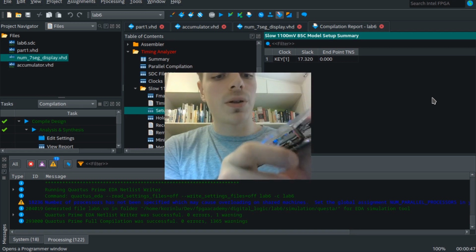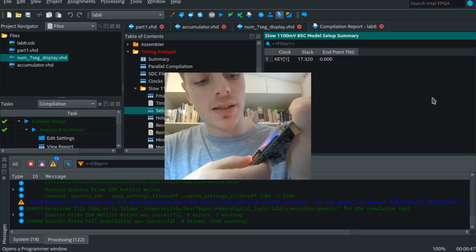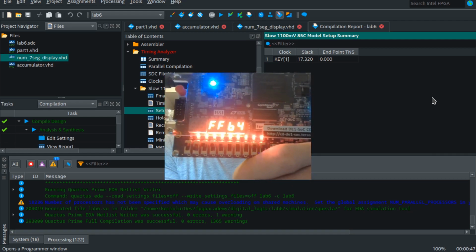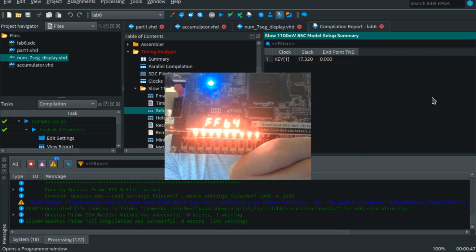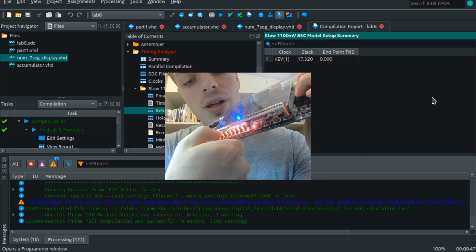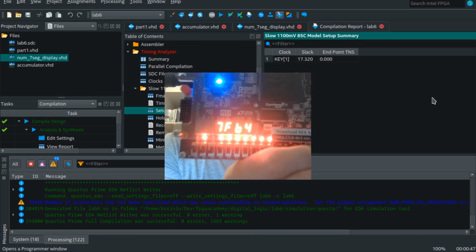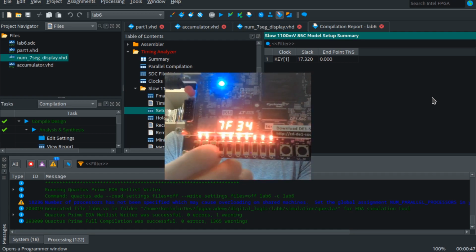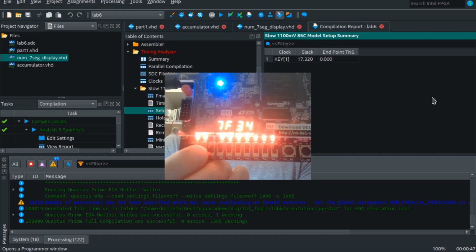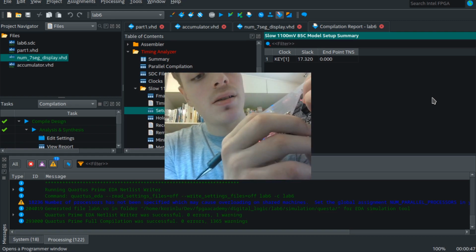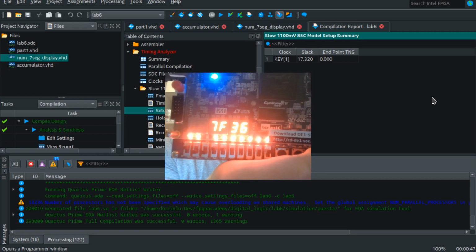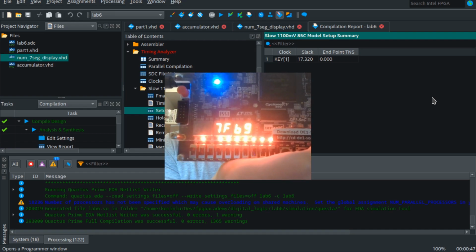So let's look at overflow. If I put a really big negative number, the maximum. So now we have a positive number, and we will subtract. Now we will subtract a very big positive number like this. Now you can see another, the 8 one turned on, and that means we have overflow. We added two really big negative numbers, and the result was positive. So you can see it works.